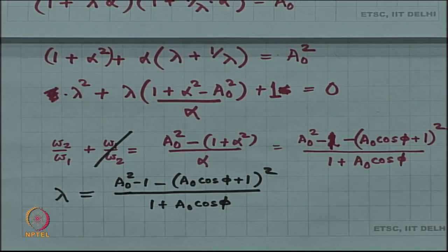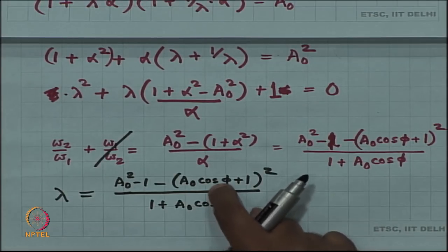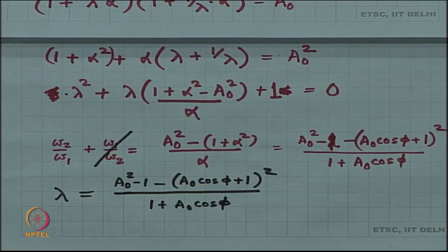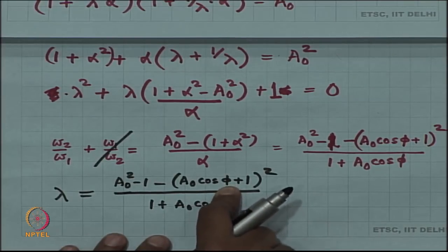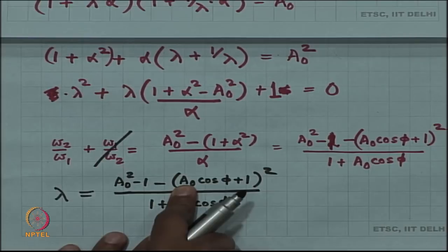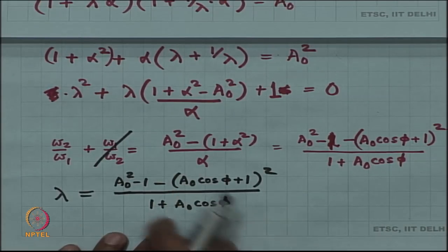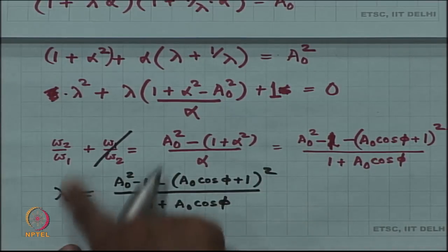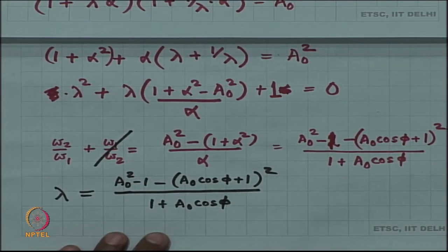And now all you have to do is, let us say your company manager tells you that I need an op amp of a certain phase margin phi and a certain DC gain A naught. Immediately you can set up your work and you can work out what is the ratio of the two poles that you are going to have in this op amp.